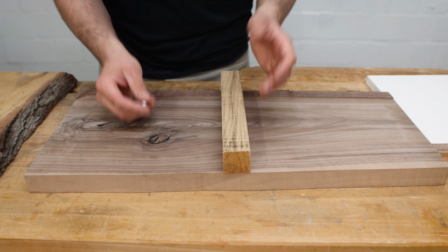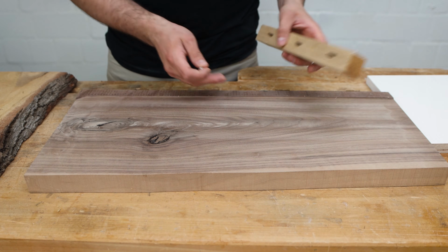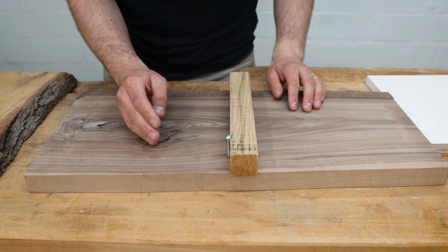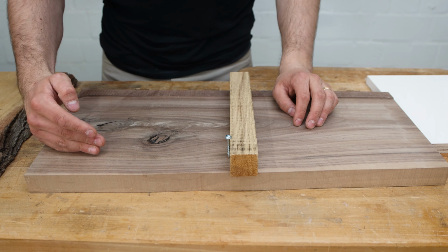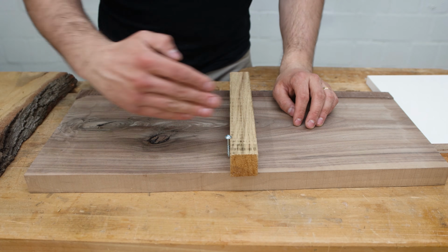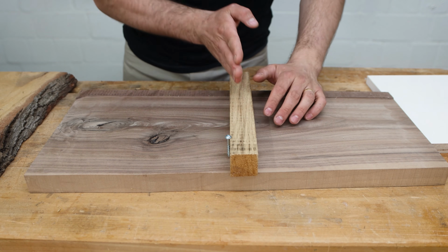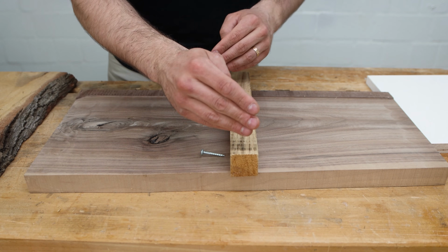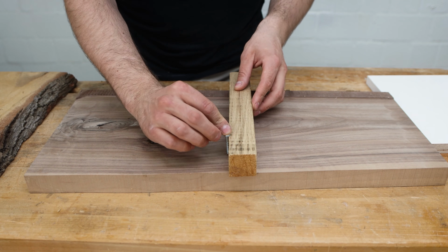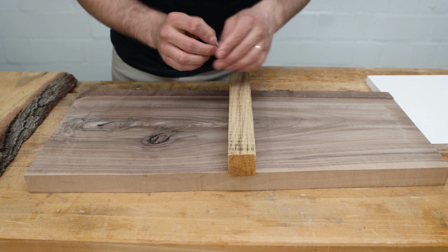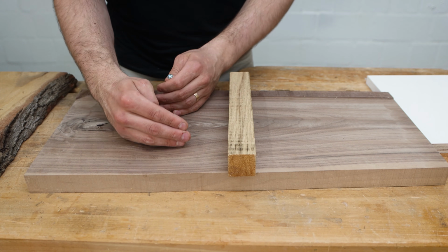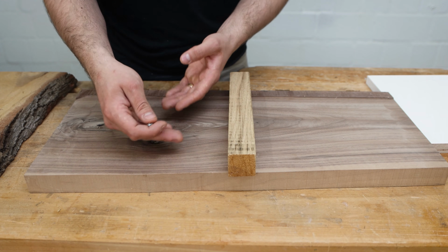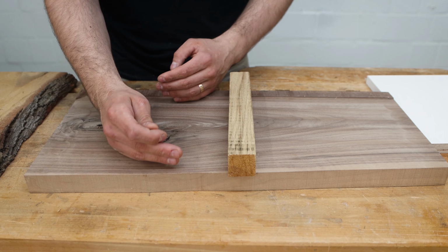Okay, let's get to the first construction method. Let's assume we have a tabletop and we want to attach our base to it. If you just take your base and screw it to your top like this, we will have a cross grain joint. That means the grain of the top is running in this direction and the grain of our base is running in this direction. As we know, wood moves in this direction here and the base does not move in this direction. This means if we just screw it down like this, 1, 2, 3 screws, the wood in the top cannot expand and contract freely. It will crack eventually.